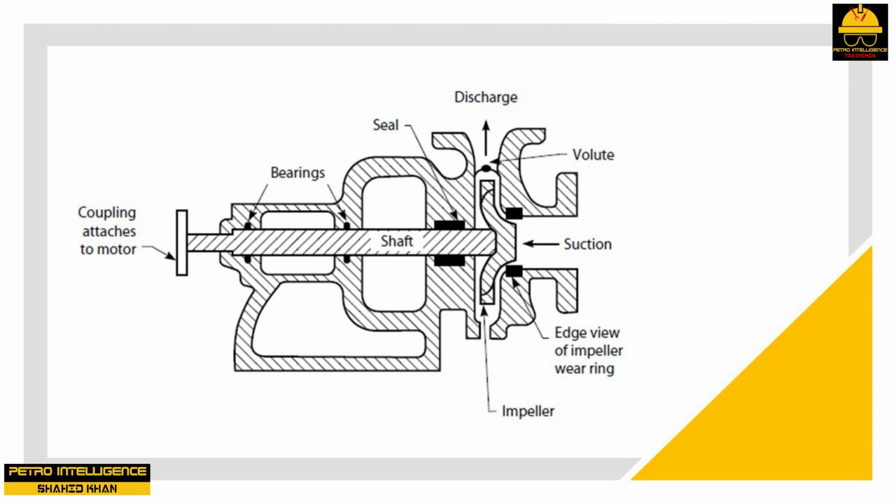The impeller is the working part of a centrifugal pump. The function of the impeller is to increase the velocity or kinetic energy of the liquid. The liquid flows into the impeller and leaves the impeller at the same pressure. The location of the oval dot shown at the top of the impeller in the picture is called the vane tip. The pressure at the vane tip is the same as the pump's suction pressure. However, as the high-velocity liquid escapes from the impeller and flows into the volute, its velocity decreases.